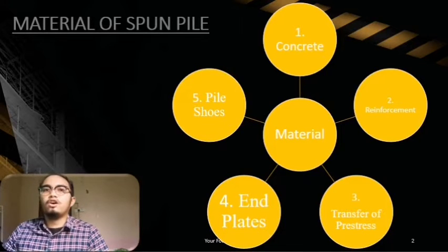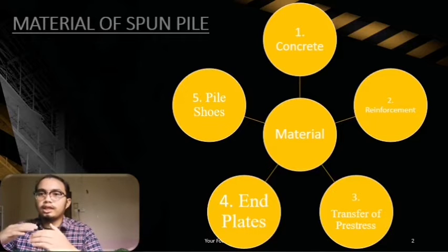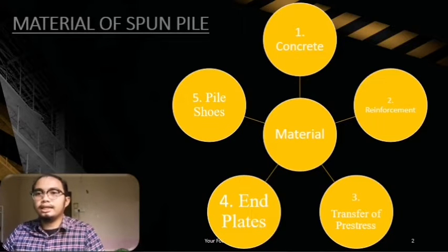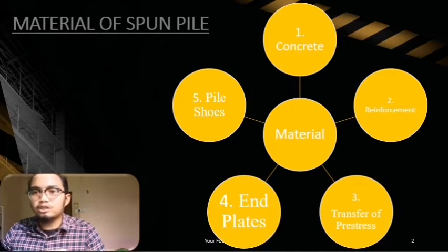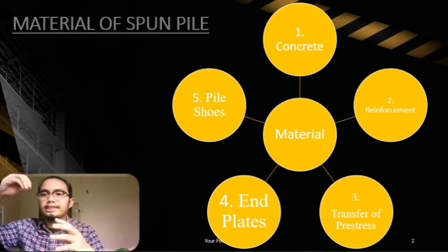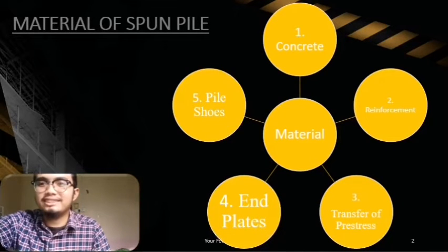and the cylinder reinforcement, and then transfer of pre-stress. Then end plate for the joint between the two piles, and the last one is the pile shoes, which help the pile to be driven easily into the soil. That's all from me.